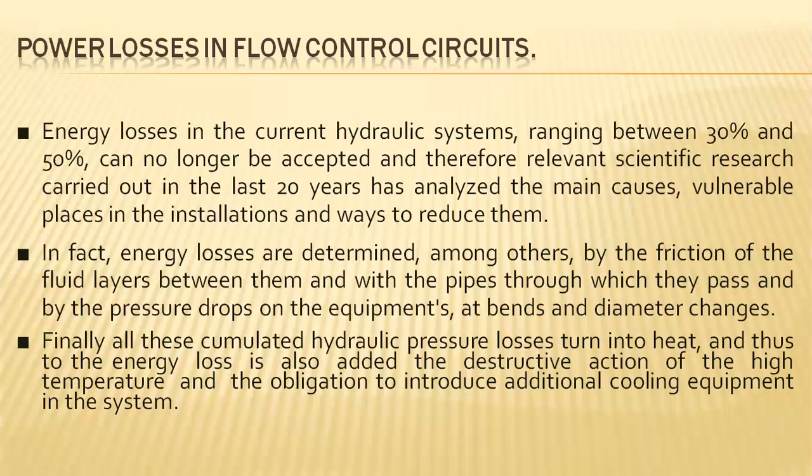Small diameter to largest diameter, and largest diameter to smallest diameter. In this range, the pressure will increase when it is reduced from large to short, and short to large it will decrease, and short to long, long to short, it will increase. So finally, all these cumulative hydraulic pressure losses turn into heat. This generates temperature, and thus to the energy loss is also added the destructive action of the high temperature and the obligation to introduce additional cooling equipment in the system.